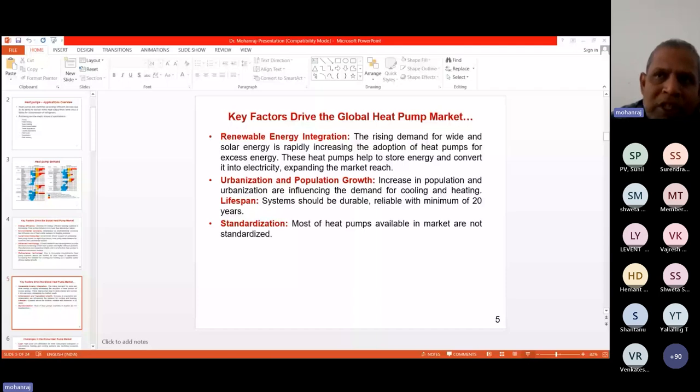So if we can go for such type of refrigerants, we can extend the range of operating temperature, but we cannot expect it to be environment friendly. Such refrigerants will have some problems with respect to their ODP as well as global warming potential. Because it is an unsaturated compound, it contains chlorine as well as fluorine. So the sudden decomposition will create an immediate environmental impact. This will be another serious issue.